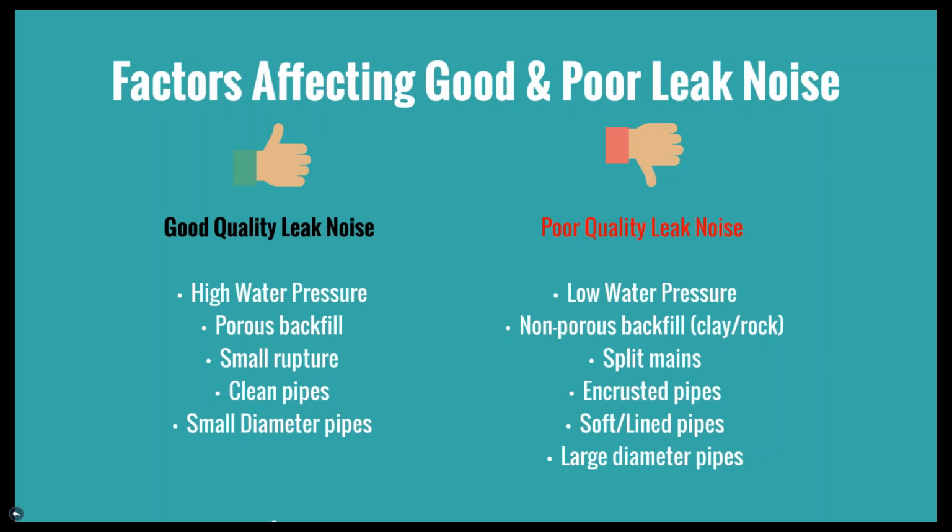There's more to deaden the noise as it goes through for picking it up with the hydrophones. Your distribution pipes are smaller diameter, and the technology that's out there is better for smaller diameter. Pretty much down the line, it's the opposite for poor leak noise. Not to say there isn't large diameter, but usually with the large diameters, you want something in the water column to do leak detection.